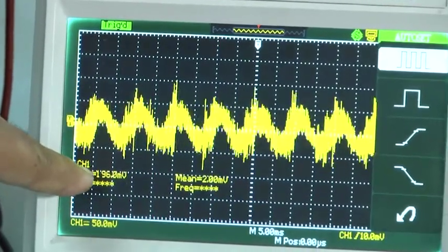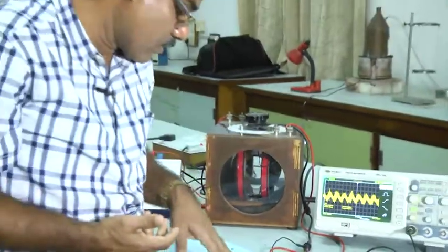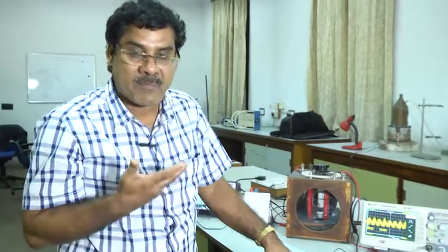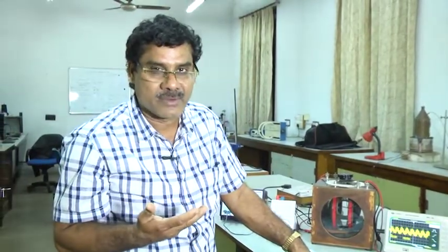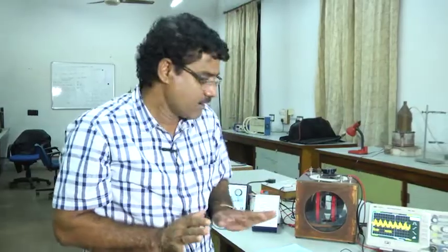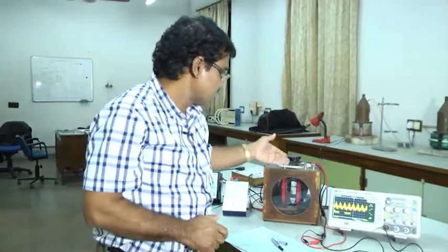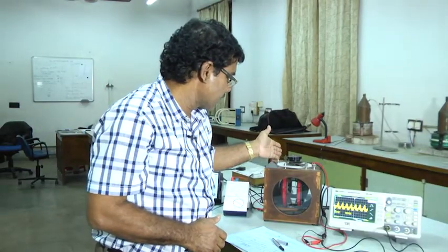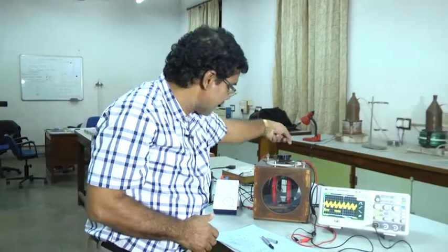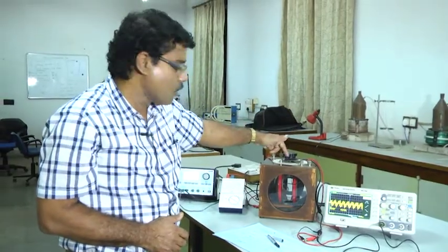You see here the reading is showing 1.9, which means 2 millivolt. So the error bar is 10 millivolt. This 2 millivolt is error noise, so we can take the reading as 0. So this is up to 90 degree. Then again you change 100, 110 up to 180.